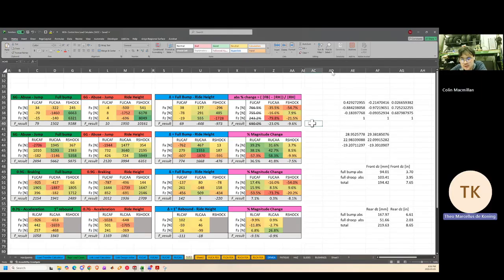That's a good question. What I think would be the most accurate way to do it would be to put a linear potentiometer on the eyelets of the shock, on both ends of the shock. You know what I'm saying? Yeah. And then sync that data up with the IMU data, and then look at those side by side. I see. So you can look at how much the shock is compressing over time, compared to the IMU data.